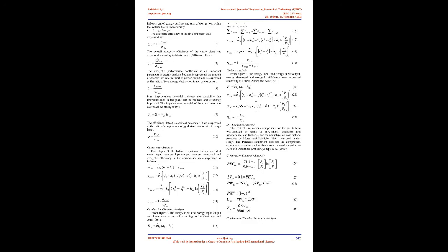Exergy losses refer to exergy that is lost to the environment, whereas exergy destruction refers to exergy that is lost within the system boundary due to irreversibility. Et al., 2018. Several researchers have spent a significant amount of time using energy and exergy to improve existing power plants. Et al., 2018 compared the energetic and exergetic performances of individual components of a 220 MW power plant and identified each component's deficiencies. The boiler, according to the author's findings, is the major contributor to overall exergy destruction, with an exergy destruction rate of 87%.